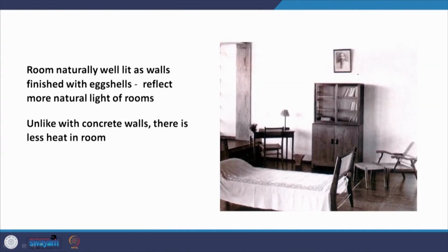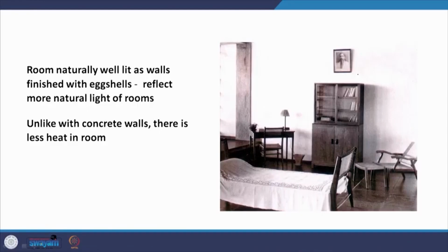The rooms by themselves are naturally well lit because the walls have been finished using eggshells and they reflect most of the natural light coming into the room. As a result, artificial lighting is not required during the daytime most of the time. So amazingly this building functions without much use of mechanical ventilation or mechanical lighting because of the way ventilation has been created and lighting is allowed to penetrate and get reflected by using these eggshells, for example. And unlike with concrete walls, there is less heat in the room because the walls are not of concrete.